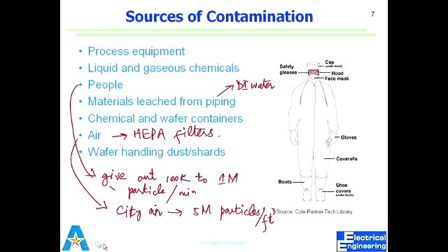So always use containers to store them. You always use containers. Use a test tube. Clean the test tube before you start your process. You need to have those squarish containers. So always after you process, it goes into a container, a closed environment. The clean room is clean, but we have many more microenvironments inside the clean room, which are cleaner than the environment of the clean room itself.